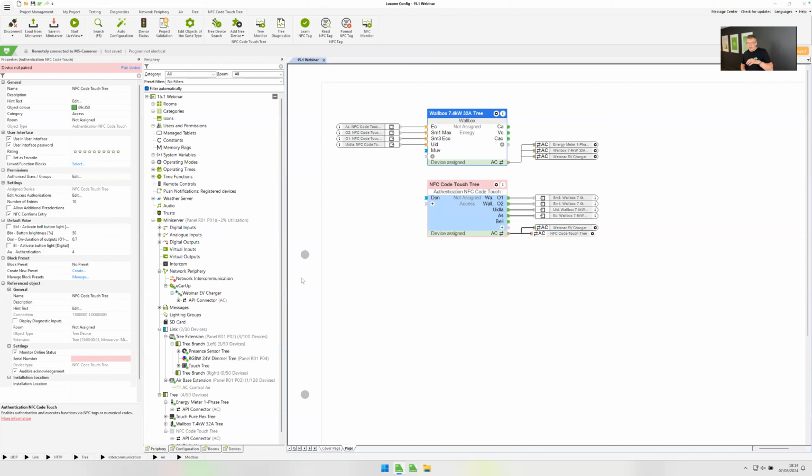With the addition of OCPP, we now have the ability to use RFID as well. So the reason why we set authentication to 4 is so that it recognizes that we need to send the RFID value from the charge card to the OCPP server for billing purposes. Otherwise, we wouldn't have the ability to do that.